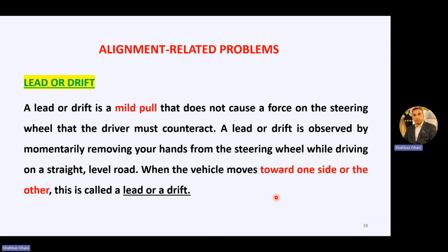The second problem is the lead or drift. A lead or drift is a mild pull that does not cause a force on the steering wheel that the driver must counteract. It is observed by momentarily removing your hands from the steering wheel while driving on a straight, level road. When the vehicle moves towards one side or the other, this is called lead or drift.